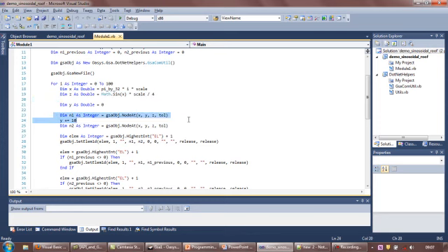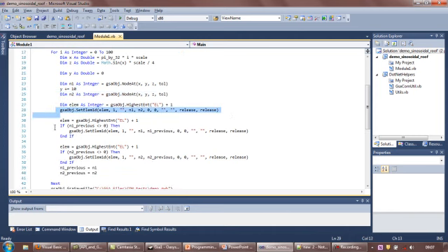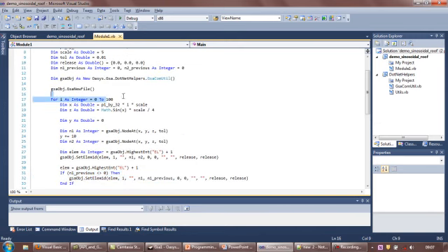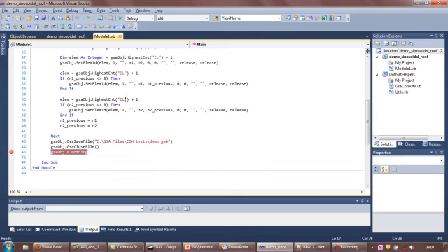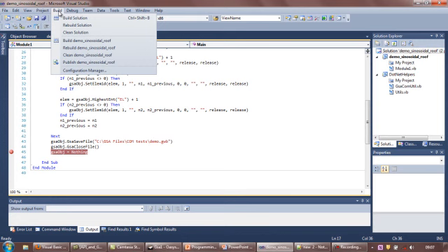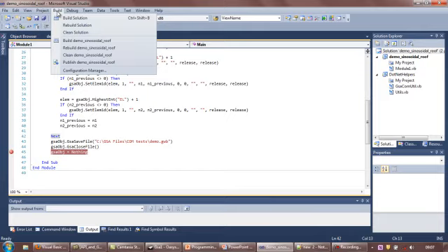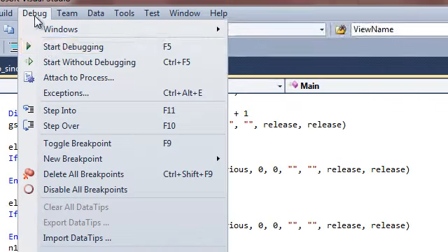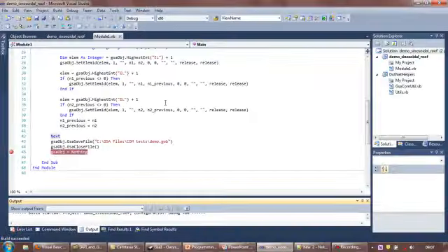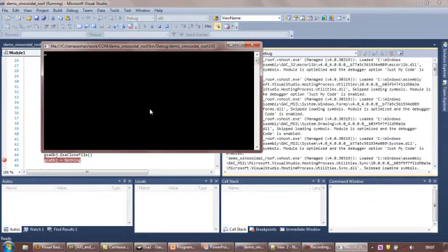And then create nodes at N1, and then add 10 to Y and create a node again, and then stitch them up with elements, and then stitch them across with elements, and so on, and then iterate this over 100 times. And if I were to run this, let's put a breakpoint here, and I've saved this model as demo.gwb. So if I were to run this example,